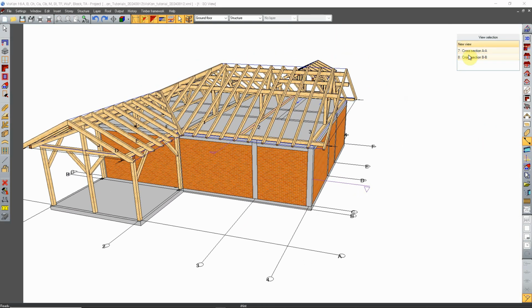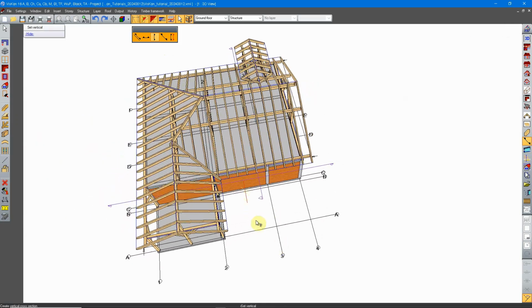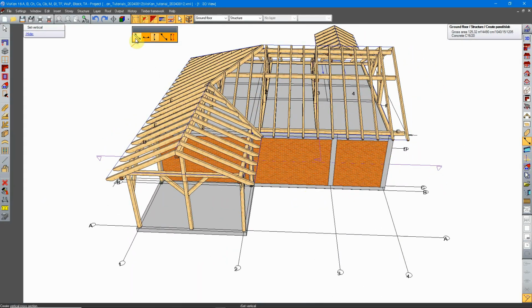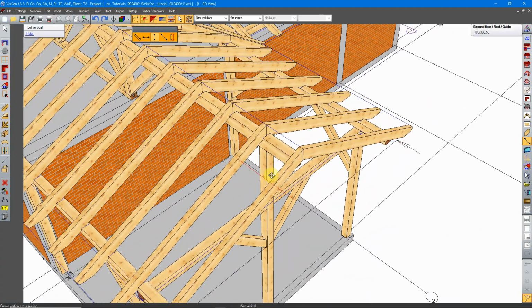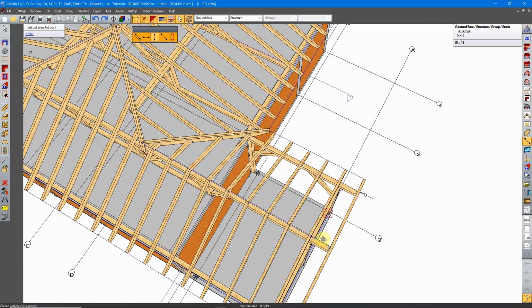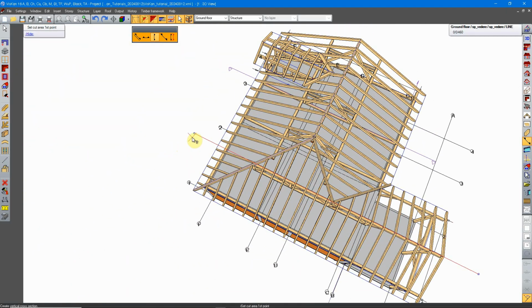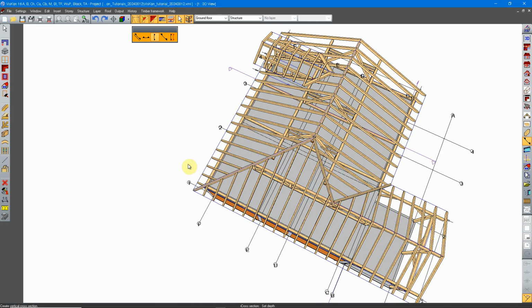We also have a vertical cross section, which is almost identical or kind of similar to the parallel cross section. The only difference is that all we need here is a single point to go through. I'm selecting the ridge here. Now I'm facing this direction.